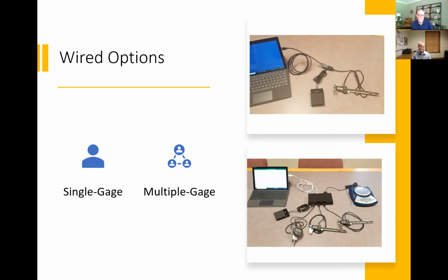So if you want to put a device with a 9-pin serial or a 15 or 20-pin serial, we have to have an adapter cable that gets us from that serial cable connector into a 10-pin Digimatic. We offer those types of things. It is still nice to have that option on the back for something like that.